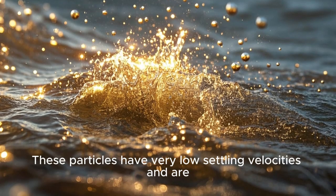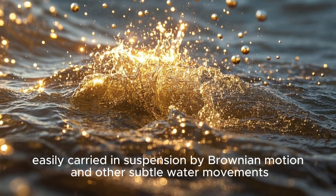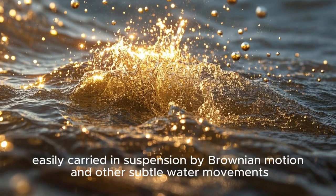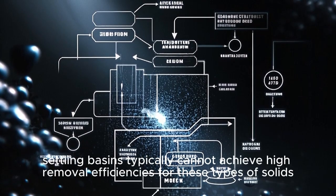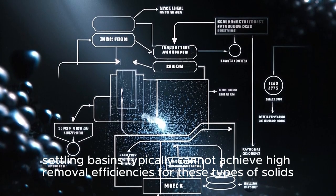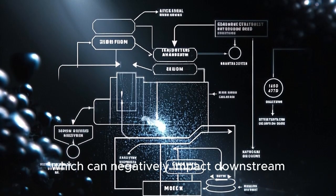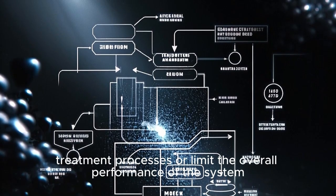These particles have very low settling velocities and are easily carried in suspension by Brownian motion and other subtle water movements. As a result, settling basins typically cannot achieve high removal efficiencies for these types of solids, which can negatively impact downstream treatment processes or limit the overall performance of the system.